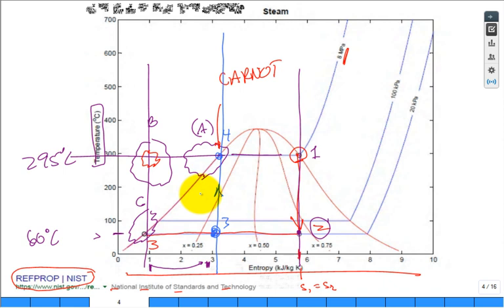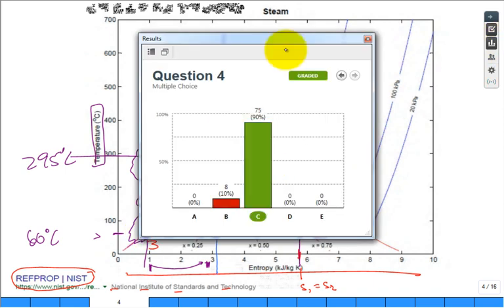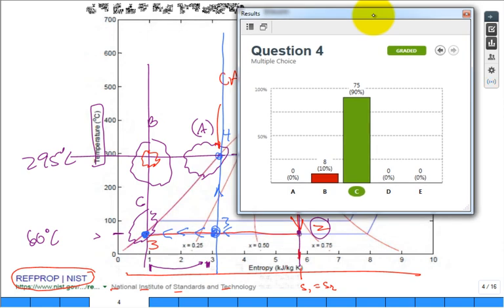The Carnot is the frictionless cycle that can't be implemented, but how close can we get to it? We can't get to it. But the ideal Rankine is as close as we can get. What you have to do is don't stop there in your condenser. Go all the way over here and move state 3 over there. Now, once state 3 is over there, the question is on a TS diagram, where is the new state 4? Let's take a look at what they said. They say it's down by C. And it is. It's down by C.